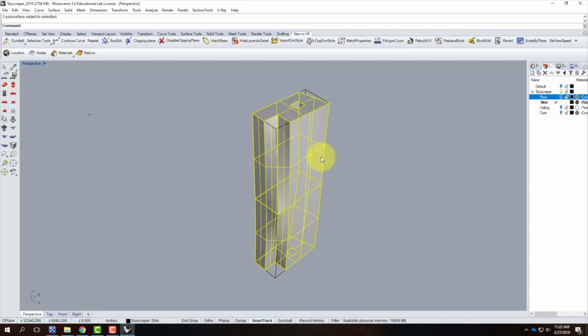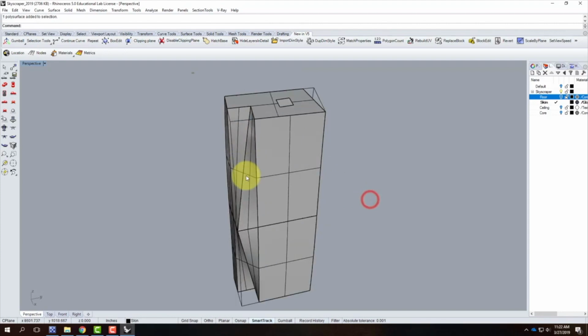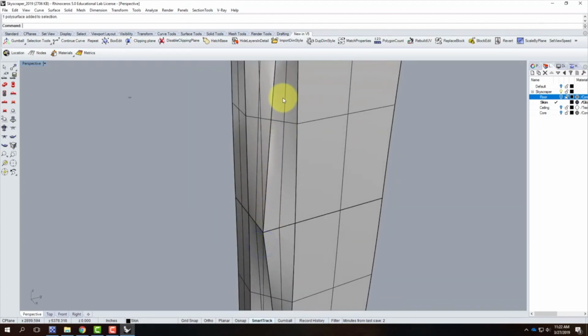And remember that this has to be done with what are called ruled surfaces or lofted surfaces, because at any point along the side, there is always a straight line. So if I looked at this twisting surface here, there's a straight line from here to here. If I moved up this edge and I went across, there's still a straight line there. It's not bulging out in 3 dimensions. So what we don't want is curvature in 2 directions.